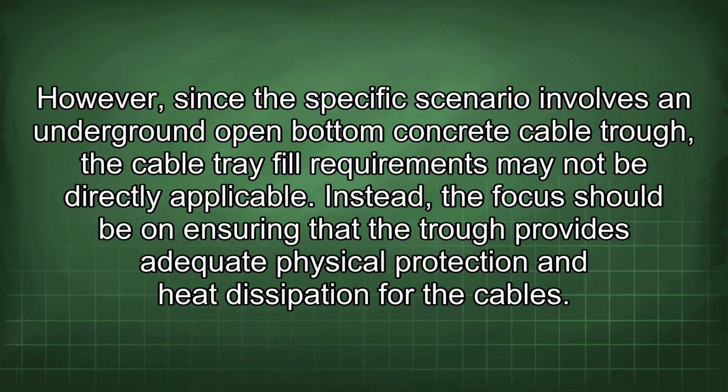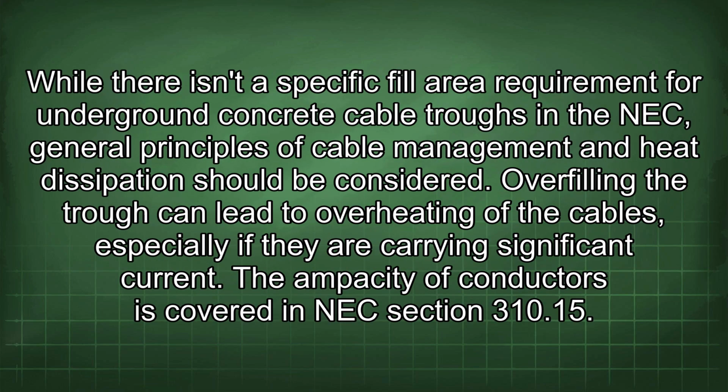However, since the specific scenario involves an underground open-bottom concrete cable trough, the cable tray fill requirements may not be directly applicable. Instead, the focus should be on ensuring that the trough provides adequate physical protection and heat dissipation for the cables. While there isn't a specific fill area requirement for underground concrete cable troughs in the NEC, general principles of cable management and heat dissipation should be considered.